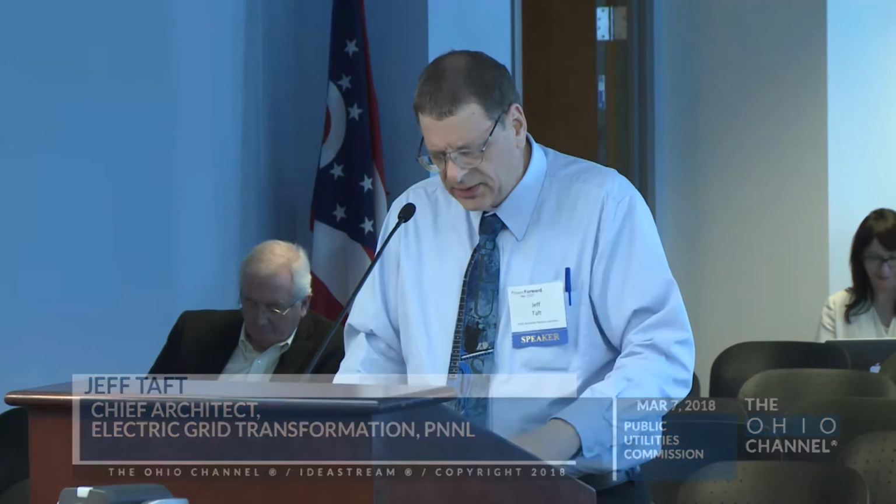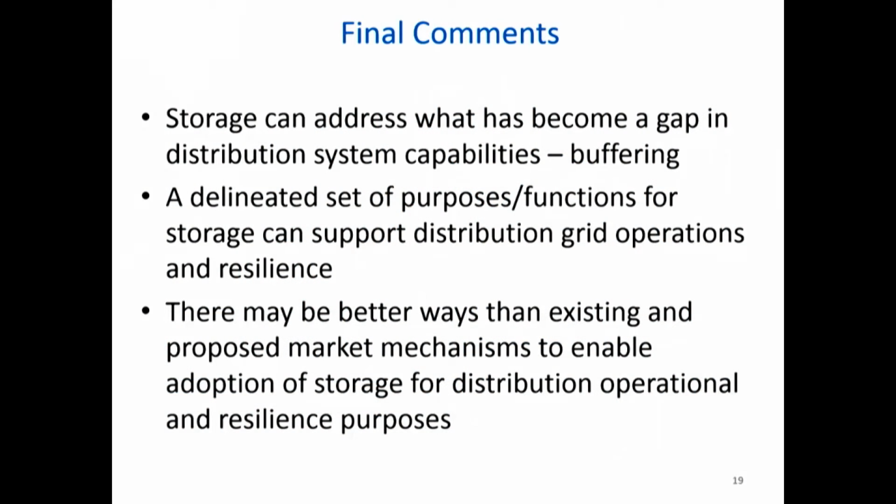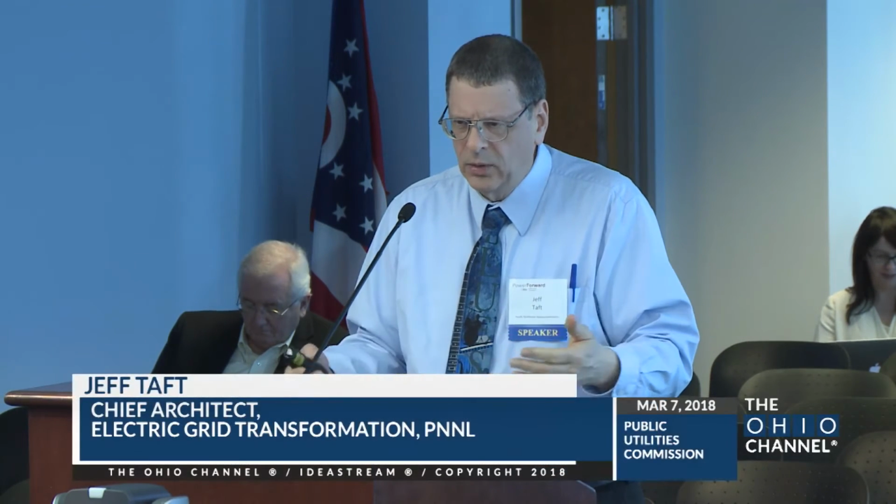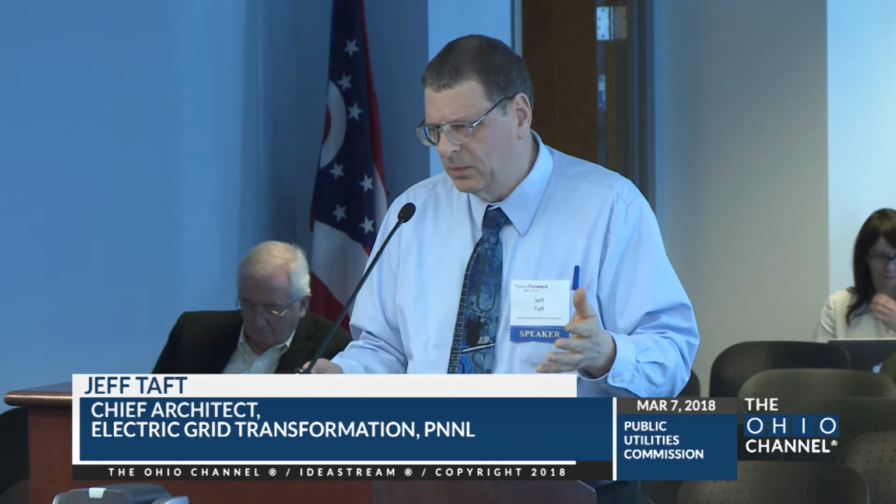So why would you want the storage to be deployed there? You could say, well, let's just let storage develop in terms of things like electric vehicles and behind the meter. Let's have market mechanisms and let those storage services be bid into those markets. But the problem with that is, in terms of things like resilience and so on, that doesn't give you firm design ability. That means you don't know how to put the storage where you want it, when you want it, in the amount you want it. If you think about distribution planning, that's typically how things are done. You figure out what capacities you need and you put them in the right places at the right time. Well, if you're going to depend on this sort of organic development because they're going to be bid into a market, you don't have that much control over them, so maybe you resort to procurement methods and so on.